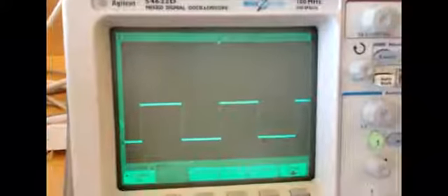So right now the scale is 5 volt, and then let's change it to 2 volt, it might be better. Right now the scale is 2 volt, and I have 1, 2 and almost 2.5 blocks. So 2.5 times 2 volts, which is the scale, means that this signal from top to bottom is 5 volt. So this is a 5 volt peak to peak, because this is one peak, this is another peak. That's why it's called a peak to peak 5 volt signal.